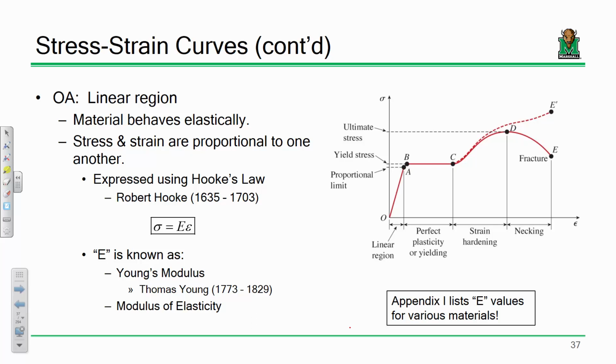If I take a look at this building, there's floor beams in this ceiling right here. There's a classroom, or there's offices above here, and there's people walking on those offices, right? There's load being applied to these floor beams. This is physics. You put load on these floor beams, they are going to deform. I would prefer that those elements remain elastic. In other words, when those people leave the room, they snap back to their original location.